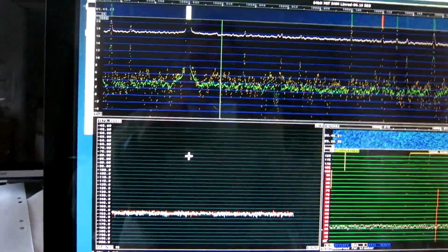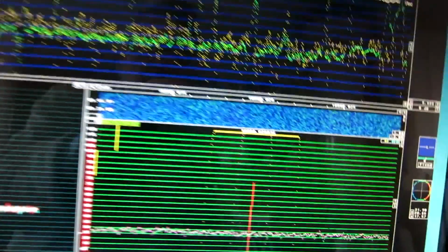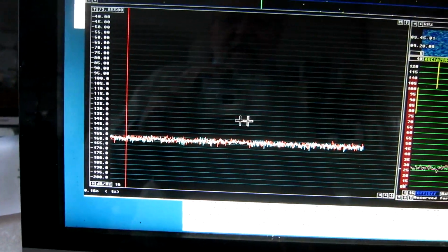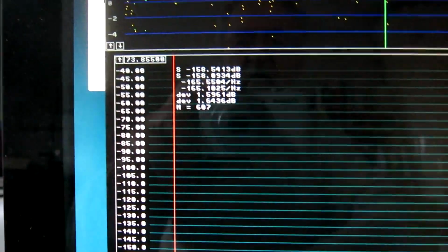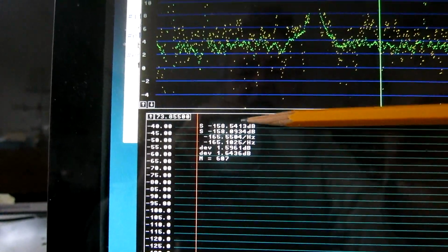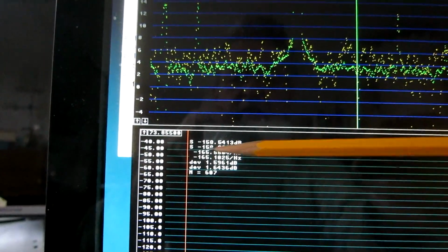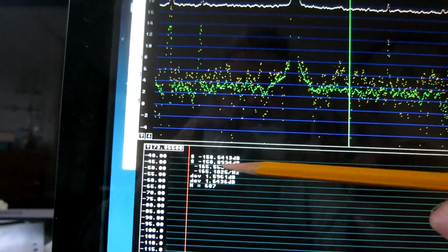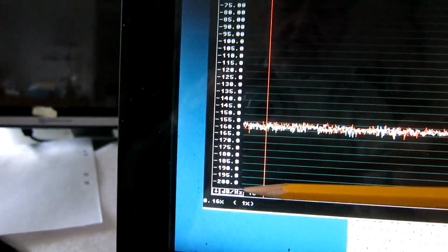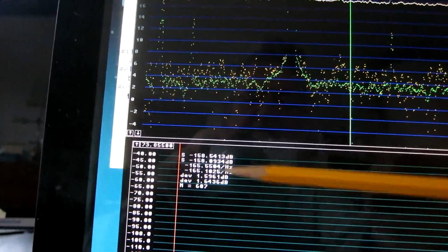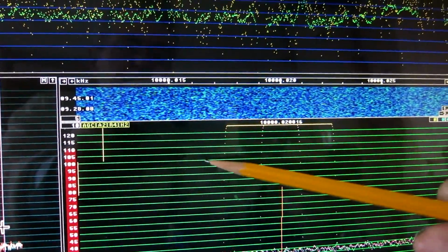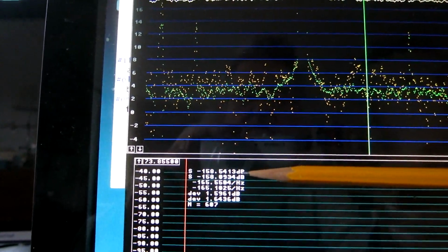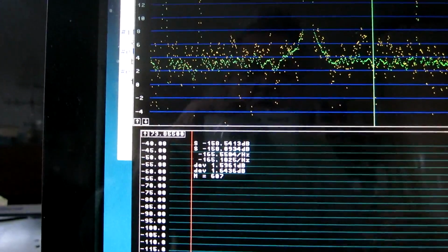The noise of this point in a bandwidth that you can see here, it's about 6 Hertz, is like this, and I can evaluate the noise, and you see within the bandwidth it's minus 158 dB, but it is also here minus 165 dBc per Hertz, because Linrad, when set into dB per Hertz, will also compute the equivalent noise bandwidth of this filter, so it can correct the observed powers here to dBc per Hertz.